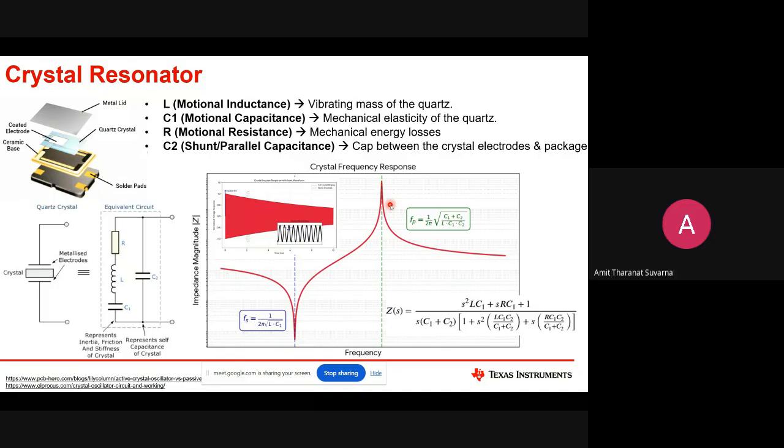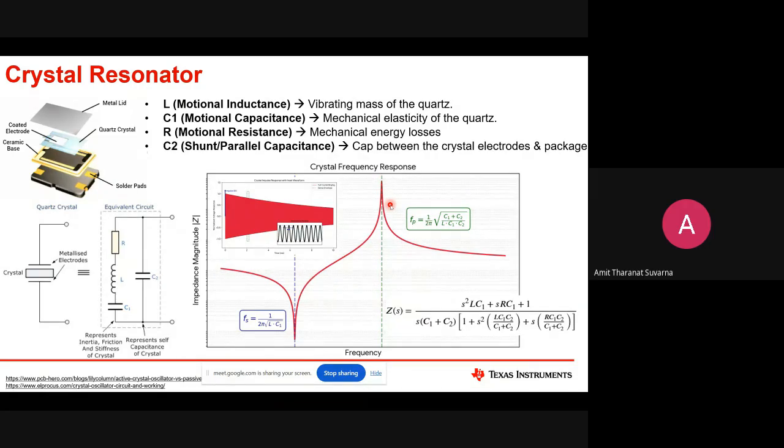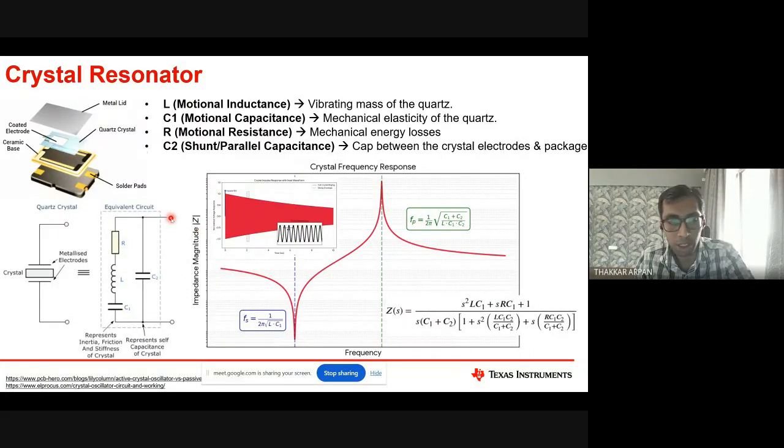So you told like the oscillator has to maintain one particular frequency, right? Yes. So if it is not maintaining it, what will be the usual cause? Suppose circuit disturbance or some bad impedance mismatch? Yes. So once you put the oscillator, parasitic capacitance can change. You connect something, it can change slightly, the parasitic capacitance, right? Yes, sir.